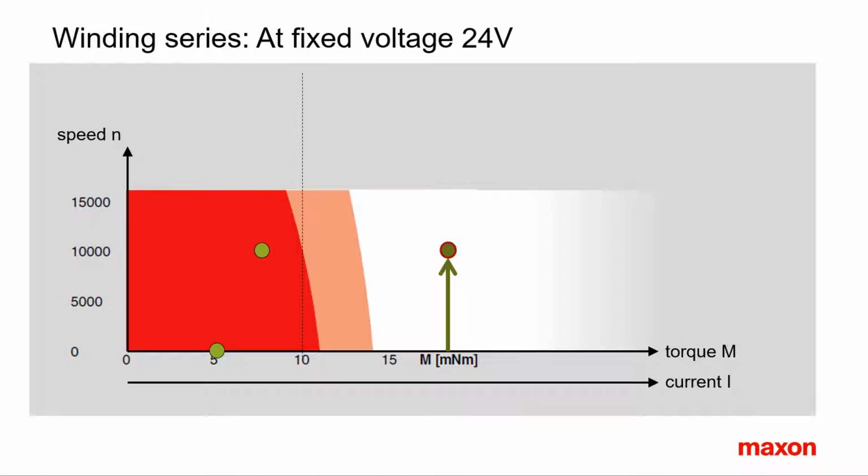For a particular application, however, the available voltage is given and the objective is to reach all the operation points with this voltage. Usually, the most demanding operation occurs at the end of the acceleration. It is the one at maximum speed and maximum torque. All the other operation points can easily be reached by reducing the voltage, a task usually done by the controller. Therefore, let's concentrate on the extreme operation point and see how the different windings can reach it with the available voltage.